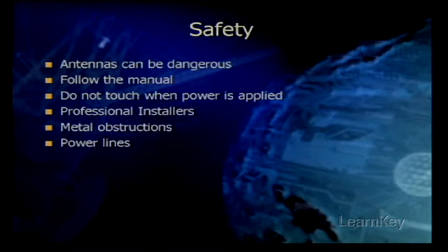And finally, anytime you're dealing with outdoor installations, always make sure that grounding rod guidelines are followed. The National Electric Code and local electric codes for proper outdoor antenna and tower grounding can be followed. Grounding rods usually should have less than 5 ohms to earth ground. The recommended resistance is 2 ohms or less. Grounding rods can prevent damage to the wireless LAN equipment and might even save the life of anyone climbing on the tower if the tower is struck by lightning. Not a guarantee, but at least it can help.